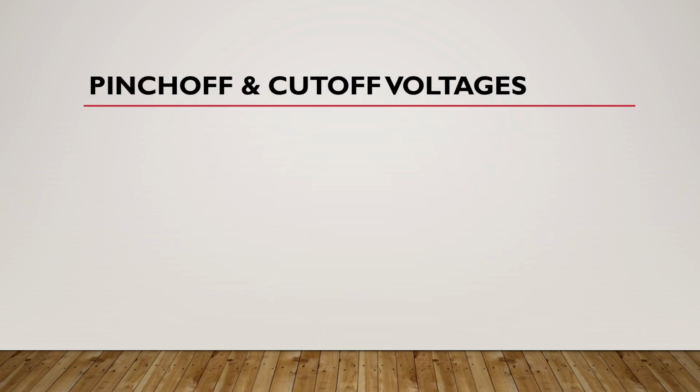Now we will understand the difference between pinch-off and cutoff voltages. As I have mentioned in my earlier slides, the pinch-off voltage VP is the value of VDS at which the drain current becomes constant and it becomes equal to IDSS, which is drain to source current with gate shorted.